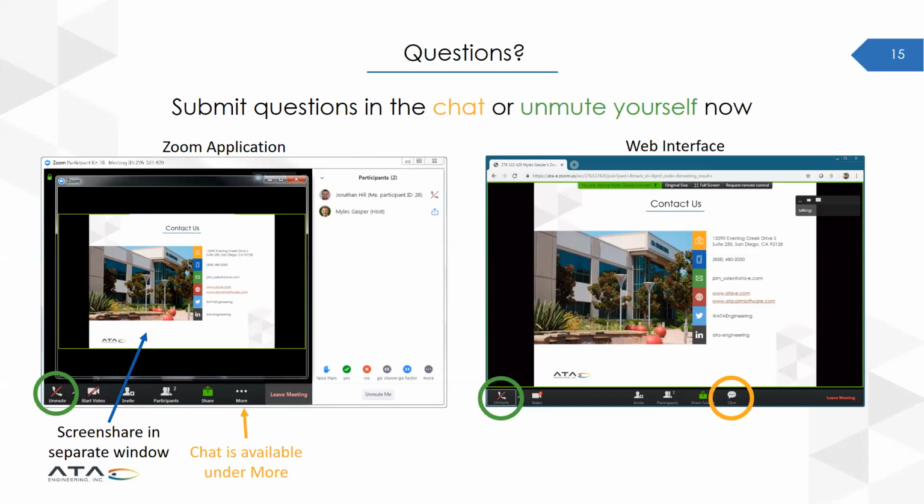So brick elements are very valuable in structural problems for solvers like Nastran, because you can use them in dynamics or nonlinear problems. And if the shapes are high quality, they can solve very fast and give you very good output. But having said that, there's a lot more work to make brick meshes. So it's a trade-off. Sometimes doing a tetrahedral mesh is fine for the particular application, like a detailed stress model that you're not going to run a lot of times. And you can get very good results if the elements are good quality. You should be able to match results between the two different element types if you've converged and done a good job with the meshing.